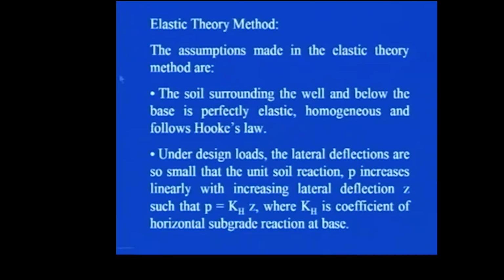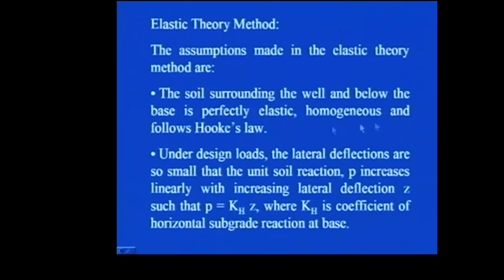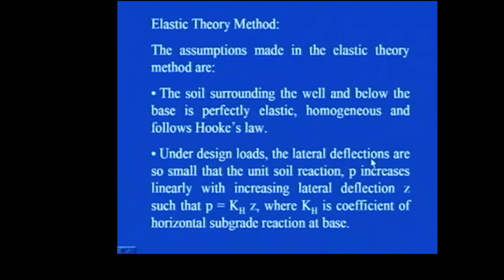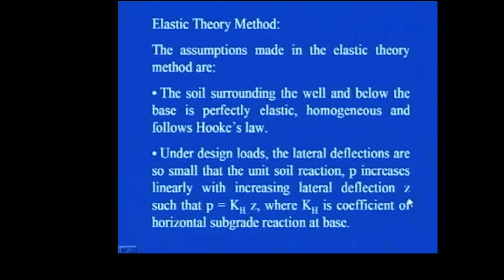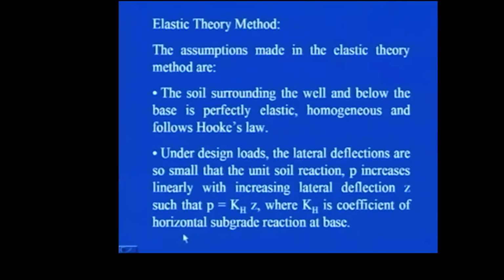So, the first assumption is that the soil surrounding the well and below the base is perfectly elastic, homogeneous, and follows Hooke's law. Under design loads, the lateral deflections are so small that the unit soil reaction, which is P, increases linearly with increasing lateral deflection, which is Z, such that P is equal to KH into Z, where KH is the coefficient of horizontal subgrade reaction at base.